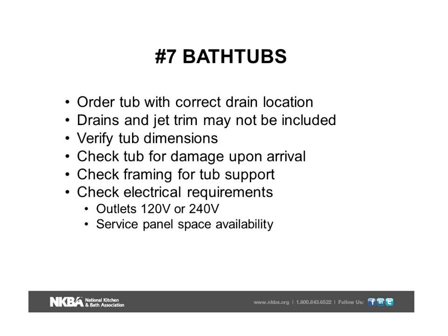In fact, the overflow for bathtubs and the drains are some of the most often missed items. People fail to order the overflow and the drain more than about anything else when they're working on the bathtub, so it can happen.